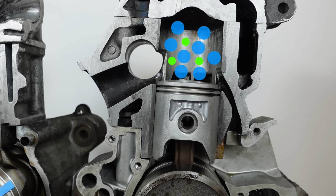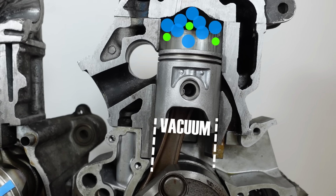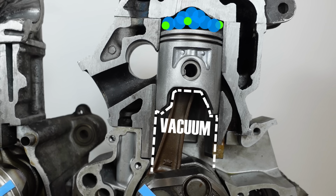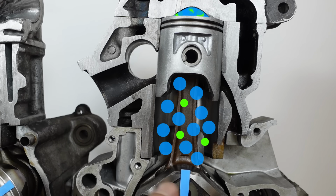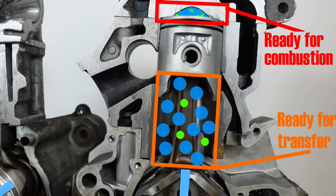Now, in addition to pushing up and compressing the air-fuel mixture, the upward motion of the piston is also drawing more fresh air and fuel into the cylinder. As the piston rises from bottom to top, it creates a vacuum below the piston. Just like in the four-stroke, vacuum is the absence of air which cannot continue to exist. And so the air-fuel mixture rushes into the cylinder through the intake port and occupies the area below the piston. When the piston reaches top dead center again, we have compressed air and fuel above the piston ready to be ignited, and fresh air and fuel below the piston ready to be pushed into the cylinder when the piston descends again and opens up the transfer port.